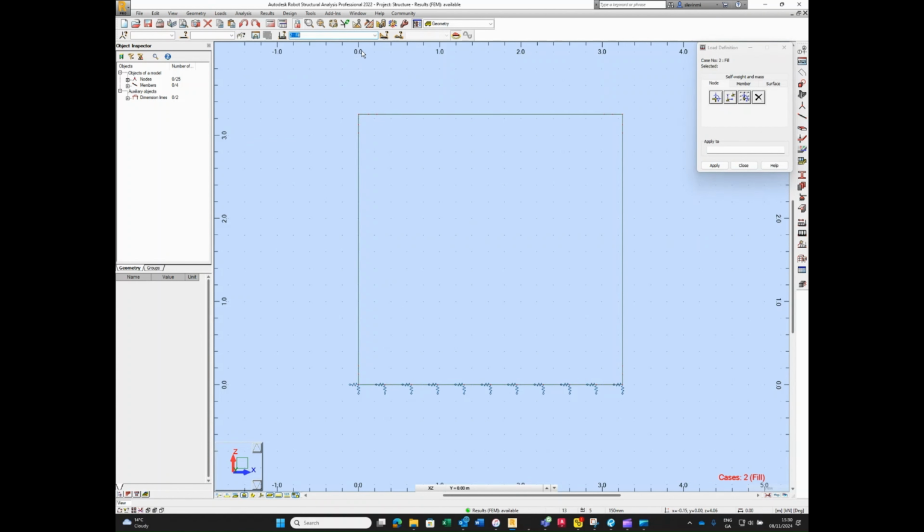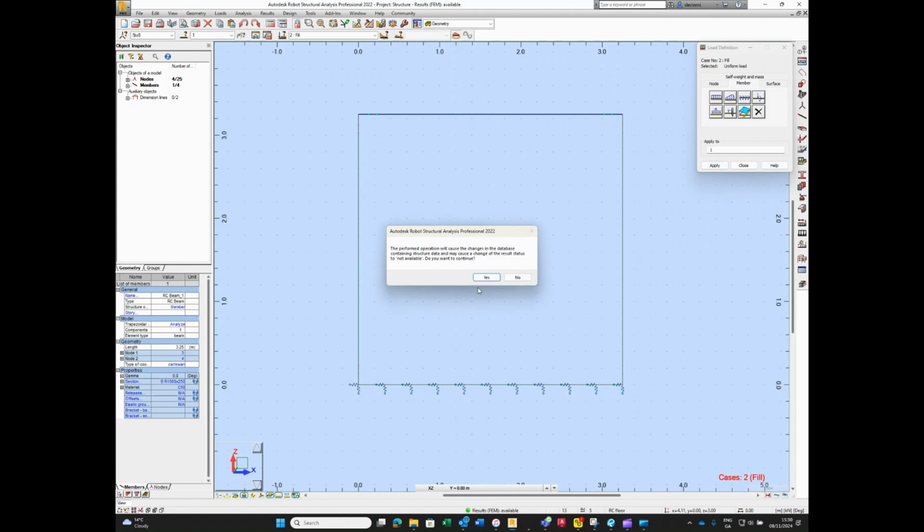We'll start obviously with a drop down menu, looking down to fill, and we can pop in for fill. So again, it's in the Z, so it's in the vertical, so we want to go on the Z axis, and we want to go minus because it's a vertical load downwards, okay. Just pick our beam then, and we hit apply.